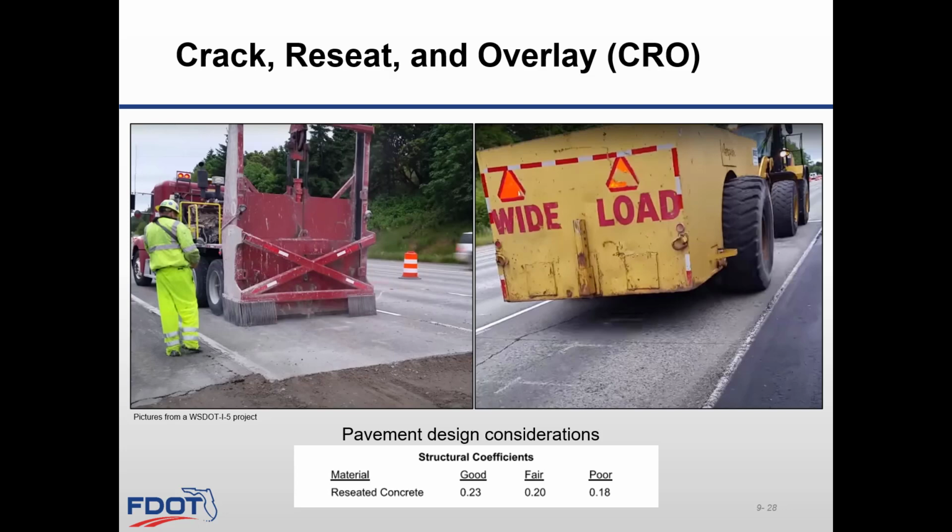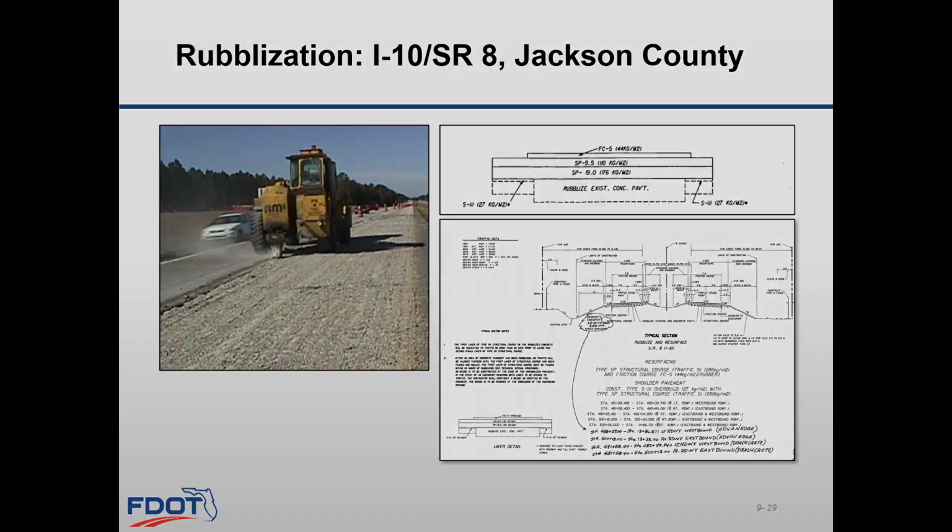If the pavement still has a large amount of water in the pavement system, using edge drains may provide an outlet for the water before the cracking and reseating operation is performed. The rubblization technique can be used on all types of concrete pavement.